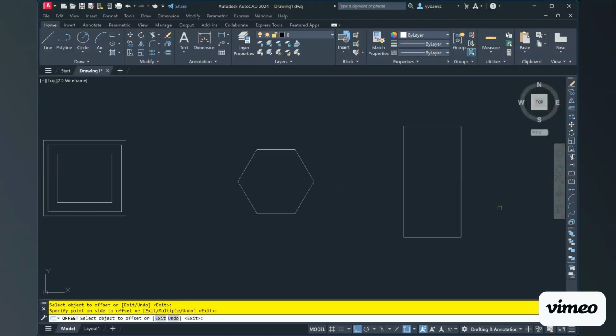If I scroll out to my other shapes that I have here, I'm going to just skip right now. Well, actually, we can go to our center shape here. And I'm going to now use another value of the offset gap type, just to show what it looks like to have our fillet line segments together.